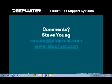I'm not familiar with clock spring pipe support systems. I've not heard of that, but I am familiar with the FRP, and in this particular question they say as long as the edges of the saddle are properly sealed. I agree with that. If the edges of the saddle are properly sealed, then water would not or could not get in between the FRP pad and the saddle or the pipe.